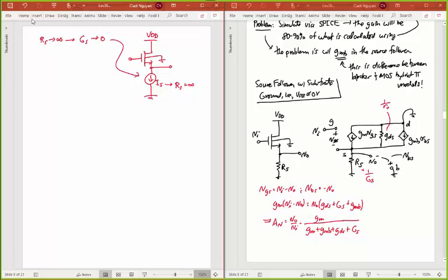And you'll see later on that that is the way that we usually try to implement MOS amplifiers, or at least source followers like this, when we're completely on chip. We make a current source here, where that current source is actually coming from another transistor. So the way this really looks like is this. Okay, we're really creating this circuit, where that's VI, this is V out. And this is some kind of bias voltage here that's biasing the whole thing.